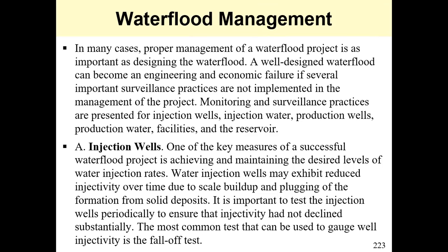So when it comes to the case of management of the water flood projects, you need to consider, of course, and you see this, what I'm highlighting kind of mirrors a little when we talked about planning for it, but it's good for emphasis. So one of the important aspects of the project to be properly managed is the injection wells. One of the key measures of a successful water flood project is achieving and maintaining the desired levels of your water injection rate. So you want your injectivity to stay good.